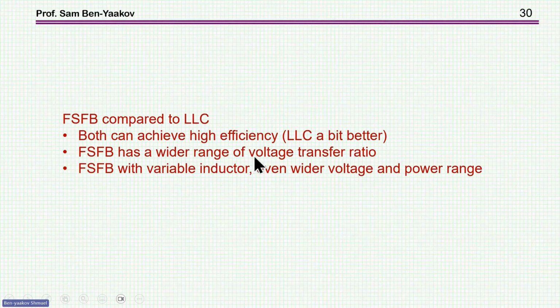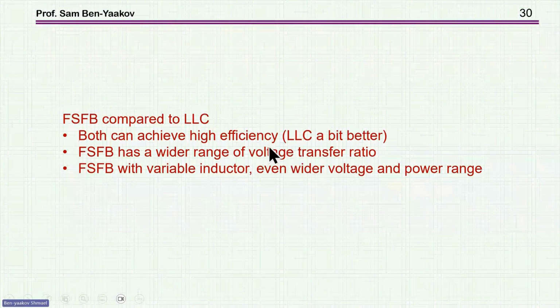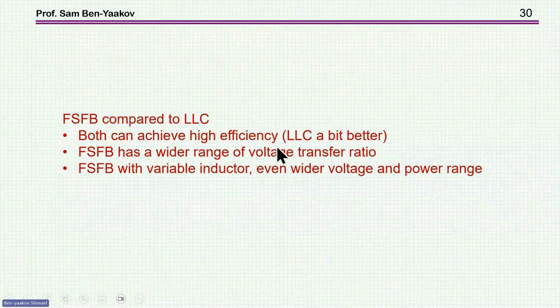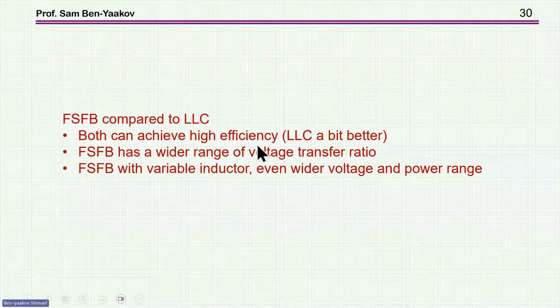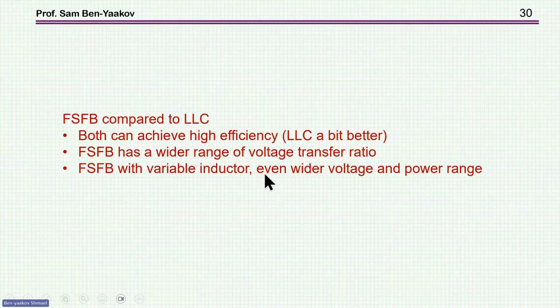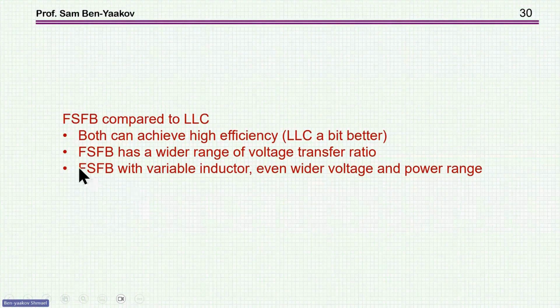The LLC has a little bit higher efficiency, but the range of input to output voltages is wider with the phase shift full bridge.